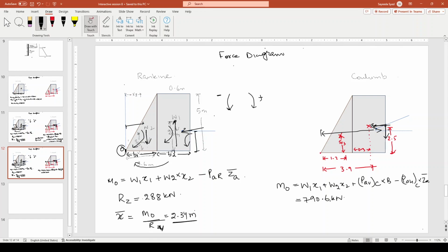So that is what we use here. A vertical load into tan of whatever is at the base, because that is what is resisting the translation movement. So we need the internal friction angle of this material and the load on this material.